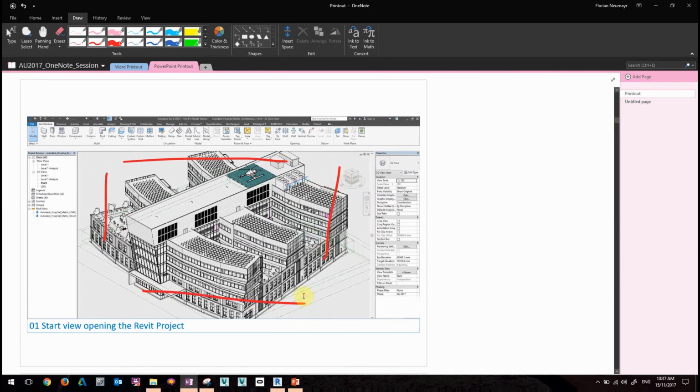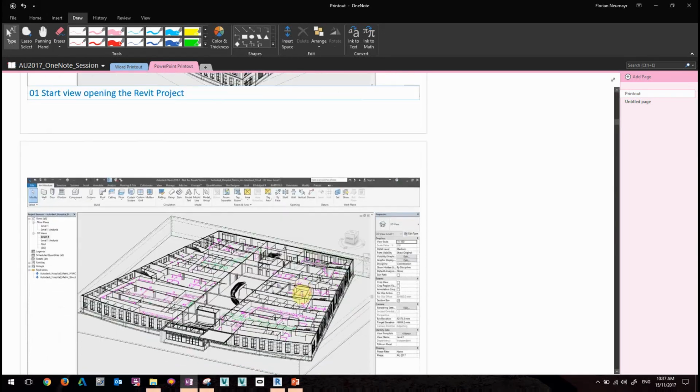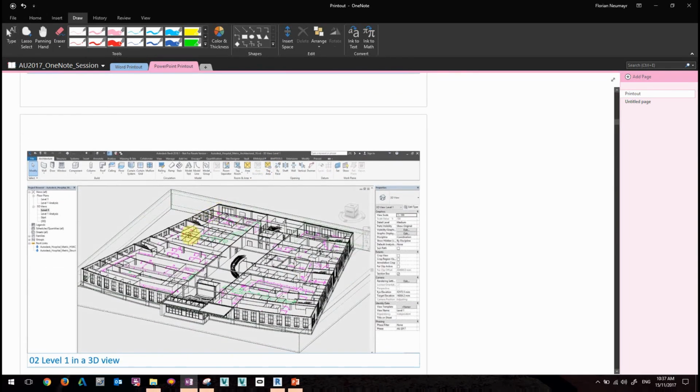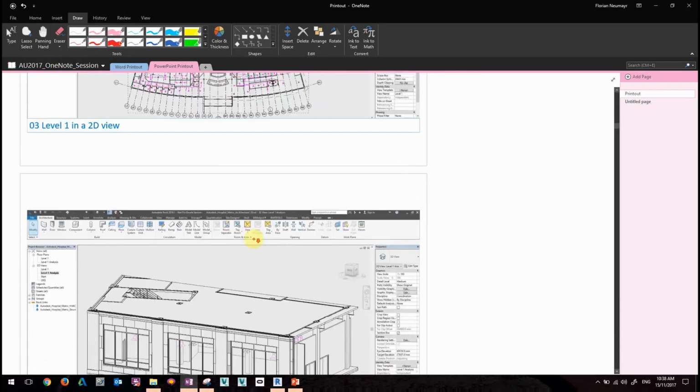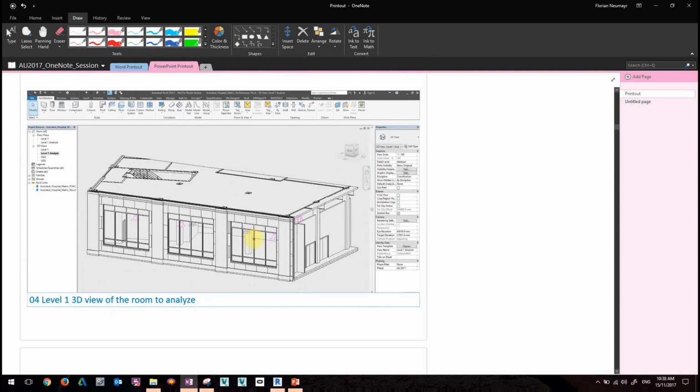We are probably all familiar with the Autodesk hospital, so it's straightforward. We can make use of common Revit techniques, for instance a scope box, or also a section box with it. If you want to use a scope box with a section box together, they are about one Revit unit, which is 1 foot apart, so we automatically get a section box around our scope box. So, preparing the view, getting the model under control, what you're actually after.